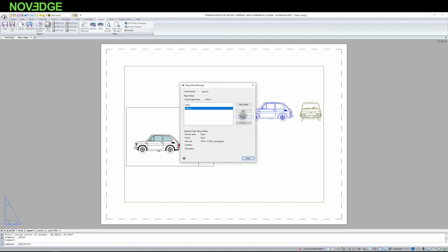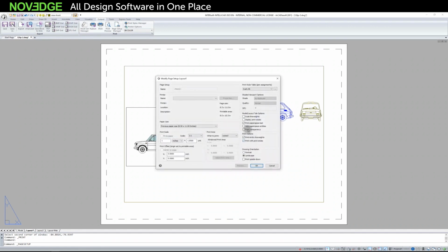So here you can define your own, add for example with information in the name, what the size of your sheet is, in what scale you want to print, and later thanks to this you can transfer these settings to other projects. Now I'll just modify it. I will choose my print styles. Here too, this transparency will not be printed. The styles work exactly the same, so the windows look the same. The only difference here is that I will choose the default printer, the PDF one, but it doesn't really matter except that I have fewer formats because I chose such a printer.